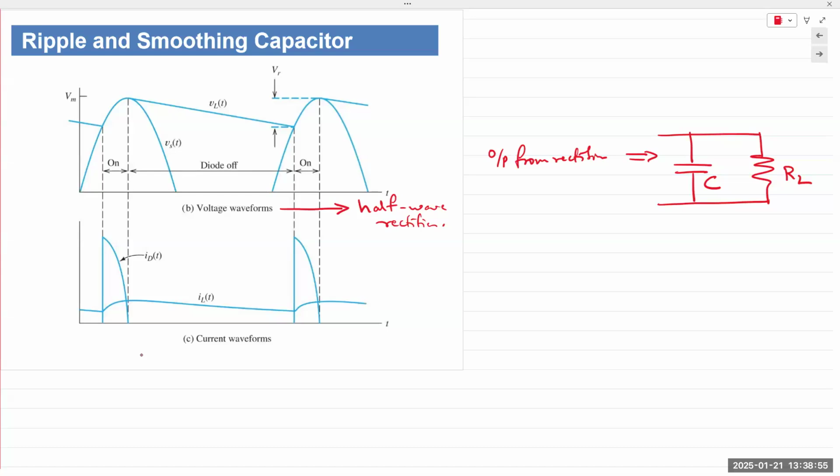So if that is the output coming from the rectifier, we can illustrate that with this peak right here. That's the diode output, which goes into the capacitor. When it's in the positive direction, the capacitor is receiving the energy. We say the capacitor is being charged. So here the capacitor is being charged.